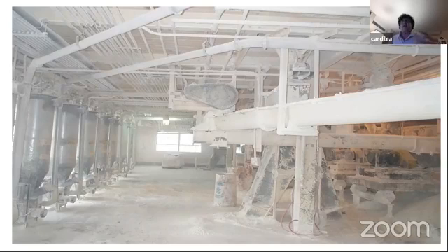It's called a peak shaving facility because in the winter time, there's a huge demand for natural gas that's larger than what the natural gas companies can supply at a given point in time. So all summer, these peak shaving places are just condensing natural gas and pumping it into this big container, 5 million gallons. And then they have another part of the plant that's literally designed to safely expand it back into a usable form, back to natural gas you can use in your house.